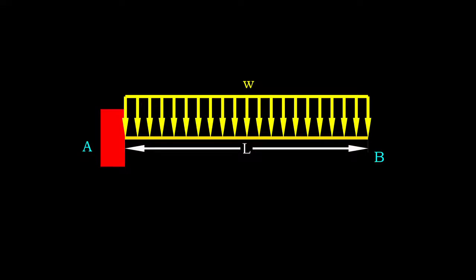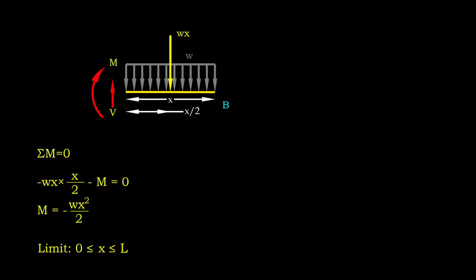In this video, we are going to look into conjugate beam method to calculate beam deflection. Let's use a cantilever beam as our example. Similar to moment area theorem, internal moment function is required to perform the calculation. Let's try another approach by setting the free end as our reference point. In this way, we may determine the internal moment function without needing to calculate the support reaction.